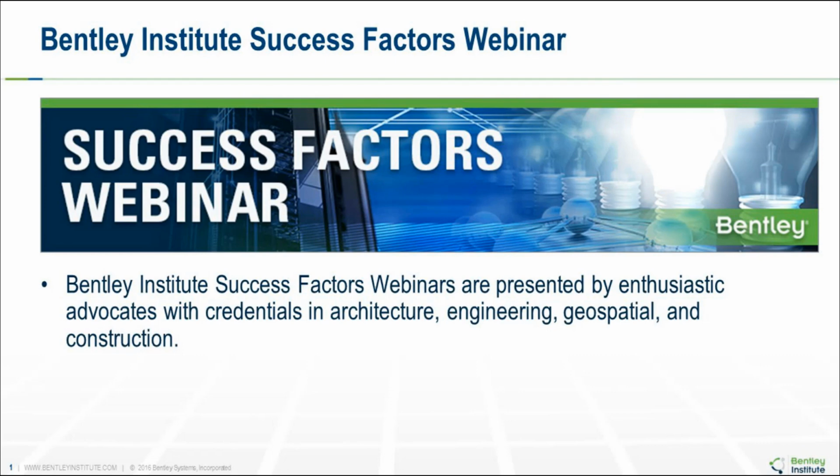As a workaround, I mentioned before that the STAAD.Pro physical modeler is a high fidelity import-export to ISM. So as a workaround, what you can do is pull in an ISM repository into STAAD.Pro Connect Edition via the physical modeler, make changes from there, and then do an update ISM operation. And that should achieve what you're after.